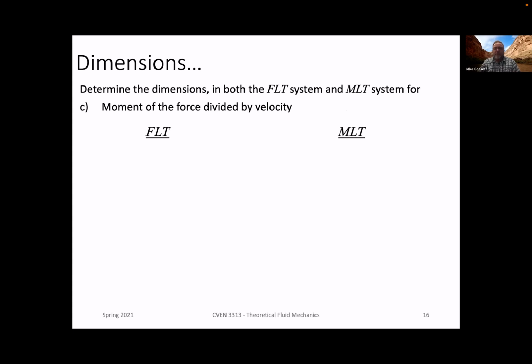It's like torque. Sorry? The torque. Yeah, like a torque. Okay, but what would that be in dimensions? Like what are we multiplying? The perpendicular distance from the force, right? Yep, times what? Distance. The distance times the actual force. Yeah, exactly. So it's the length times a force, essentially. And so the moment of force then has dimensions of force times length in the FLT system.